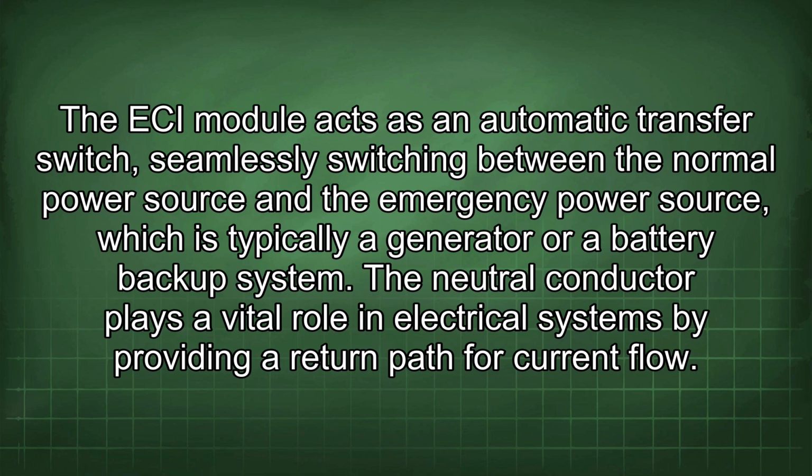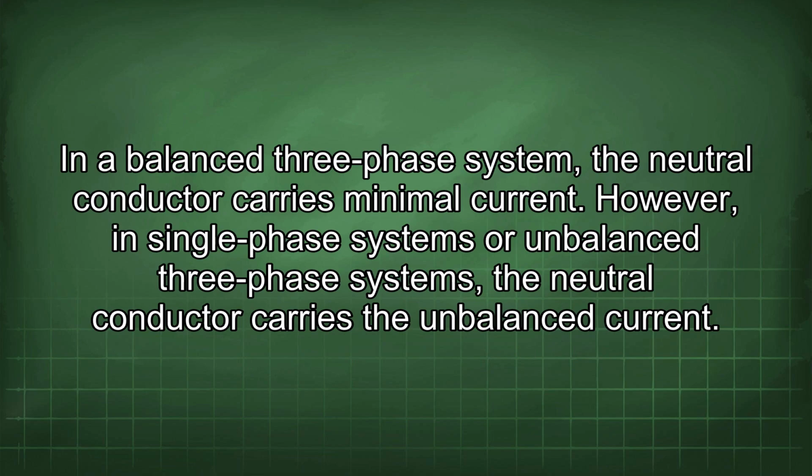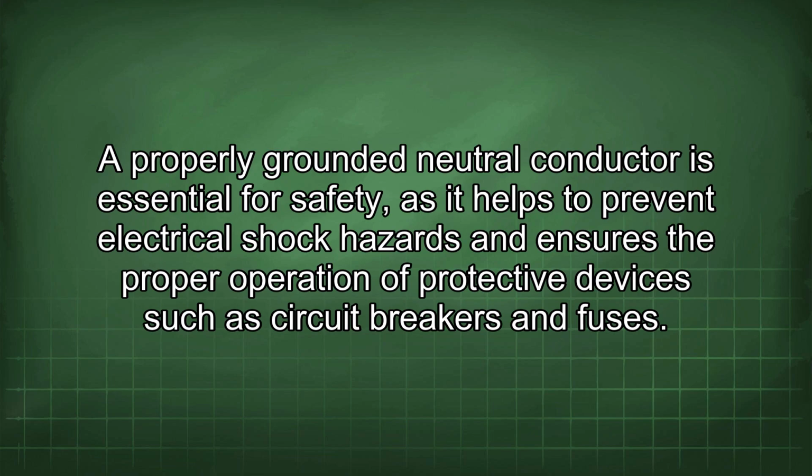The neutral conductor plays a vital role in electrical systems by providing a return path for current flow. In a balanced three-phase system, the neutral conductor carries minimal current. However, in single-phase systems or unbalanced three-phase systems, the neutral conductor carries the unbalanced current. A properly grounded neutral conductor is essential for safety, as it helps to prevent electrical shock hazards and ensures the proper operation of protective devices such as circuit breakers and fuses.